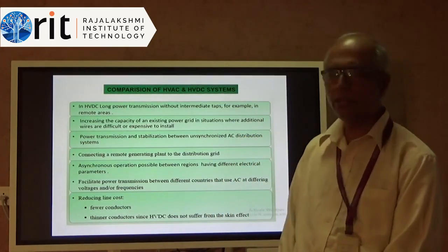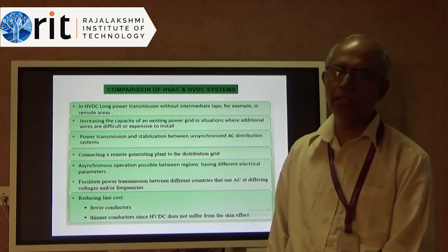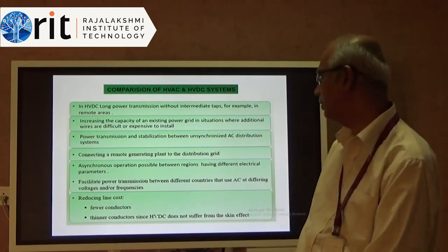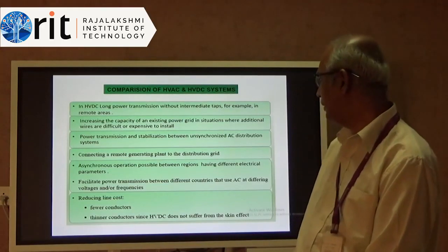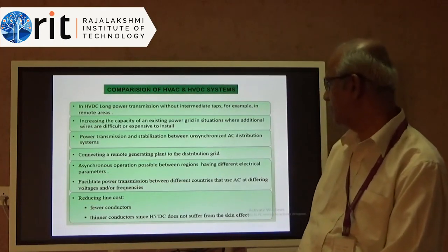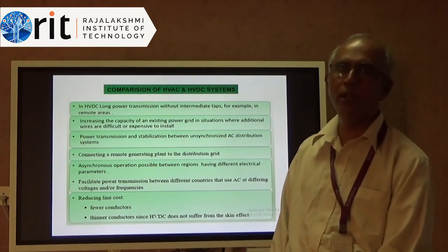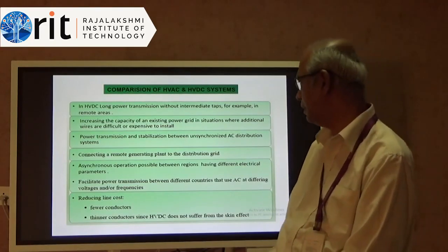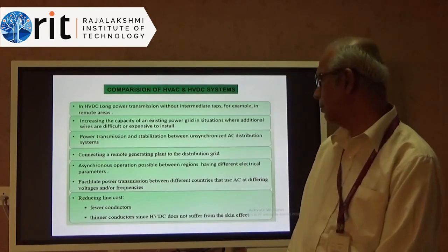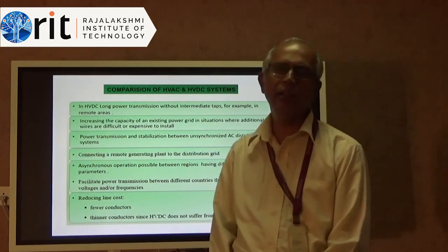Not possible with AC, because in the AC case you have to synchronize both the ends and that is not possible if they are having different frequencies. So to facilitate power transmission between different countries, probably using different values of frequency, yes, it is possible with DC. Reducing the line cost by way of fewer conductors and thinner conductors.